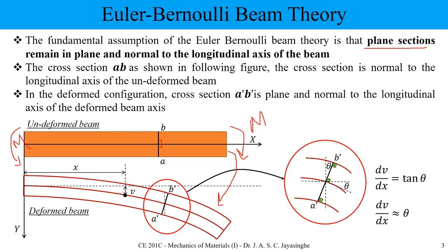After this bending, also what we can see, these are perpendicular to each other. Okay, these are perpendicular to each other. Of course, now you know about the shear effects, and this simple bending formula normally represents, or otherwise we can use another name for this one, Euler-Bernoulli beam theory. Both are the same. So Euler-Bernoulli beam theory means actually we call this an Euler-Bernoulli beam.